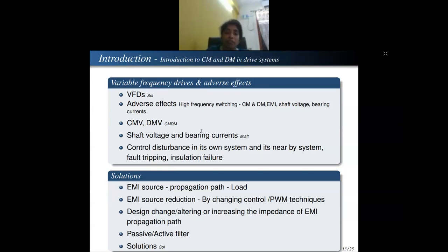So what are the adverse effects? The adverse effects are related to the processing power required at very low frequency. Say for example, the motor has 50 hertz, so correspondingly the processing of the motor requires only 50 hertz. But to achieve this high efficiency, we are using switches, which in turn produce some form of square waveform. Correct? So that will have n number of frequency components, not just the fundamental 50 hertz. It will have multiple frequency components in different magnitudes.